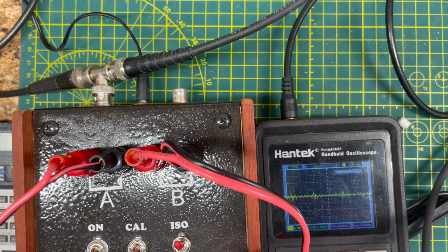All right, so right now we're on the tweeter output, and we can see at 1,000 hertz we don't have a whole lot there. So we're going to increase that till we get to the 3 dB bandwidth. Which is about right there. Somewhere around 350. And the tweeter picks up at about 2.3K.